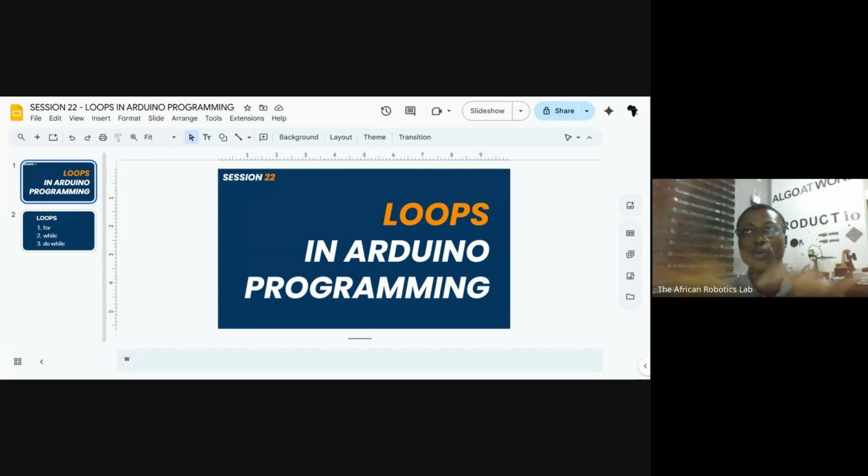For the I squared C communication protocol, we learned that it also involves just two pins or two wires. So you just connect this microcontroller's pin to the other, and then this one to the other, and those pins are SDA and SCL, serial data and serial clock, right? We mentioned that the serial data is where the data is going to be flowing, and then the serial clock, just like it sounds in the name, clock.